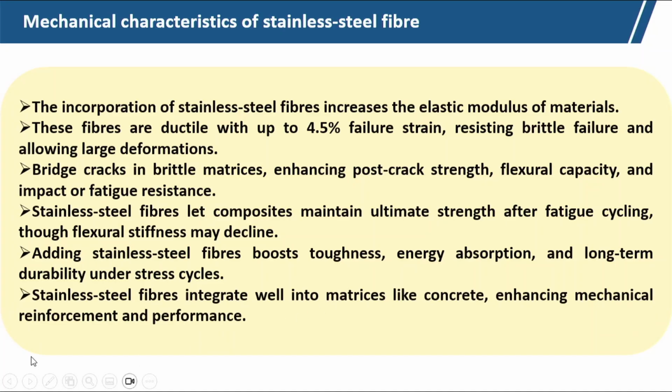So, stainless steel fiber integrates well into matrices like concrete, enhancing the mechanical reinforcement and performance. So, for concrete we can use this stainless steel fiber for reinforcement, because it has very good cohesion with the concrete and it increases the performance.